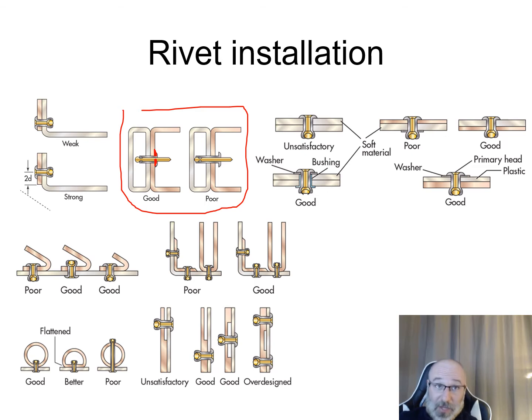So this is a visual inspection, but again, these are blind rivets, so you might not be able to see everything within a blind rivet. So also a test. Even if it's just a manual feel test, maybe you don't want these to twist. Under a certain torque, maybe they shouldn't twist at all. So that's something you can see there.